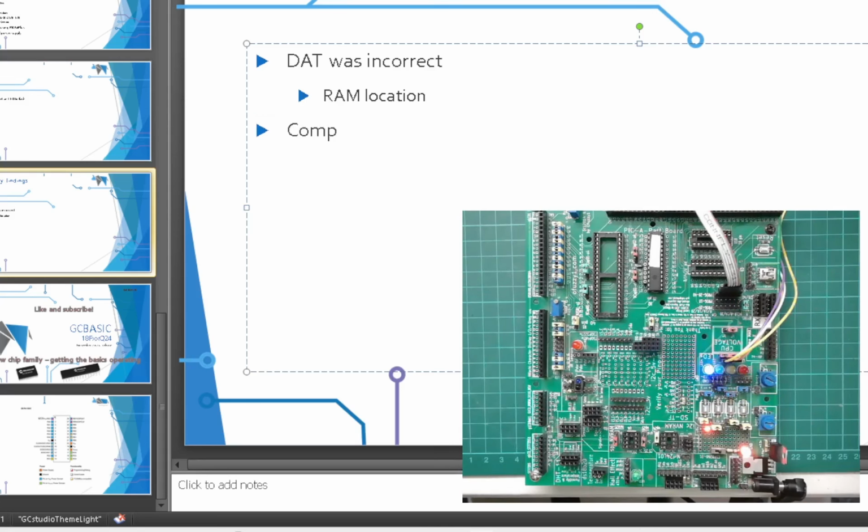Compiler does not handle port.bit appropriately. And I'll go back and undefined, because port C.7 did not exist, does not exist, okay? And I can sort of prove that later on, but that's my gut feel. Well, I know that from the data sheet.